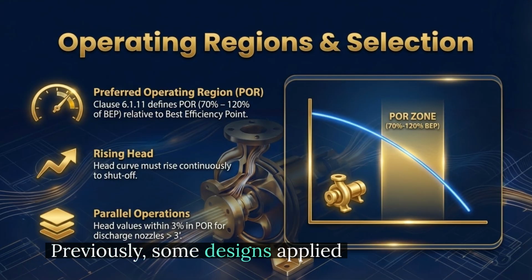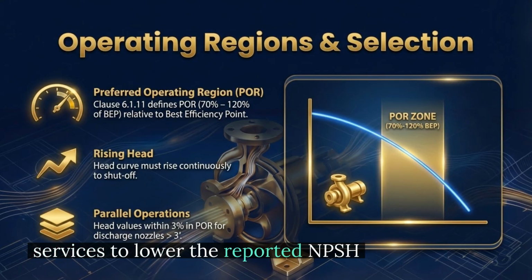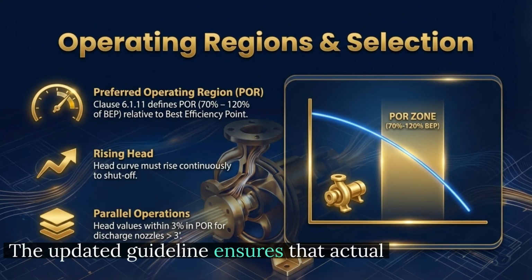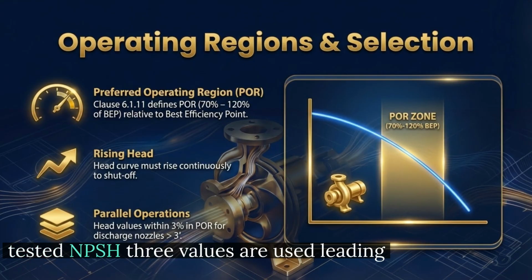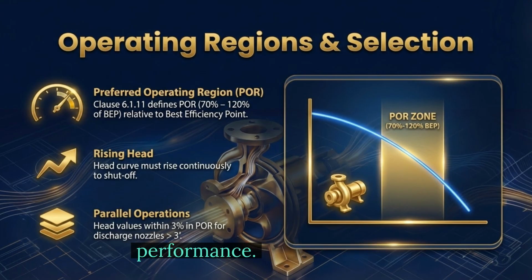Previously, some designs applied correction factors for hydrocarbon services to lower the reported NPSH requirement. The updated guideline ensures that actual tested NPSH3 values are used, leading to more conservative and reliable pump performance.